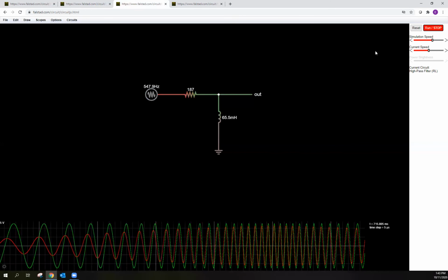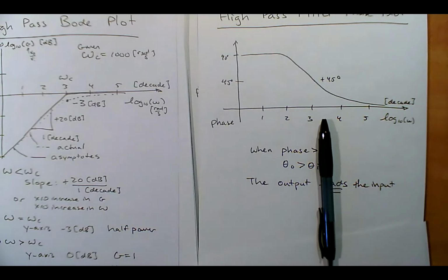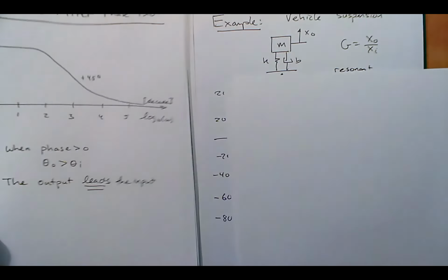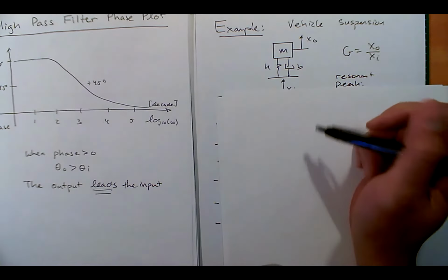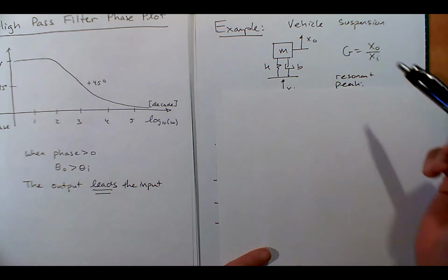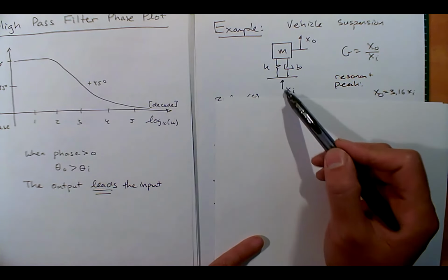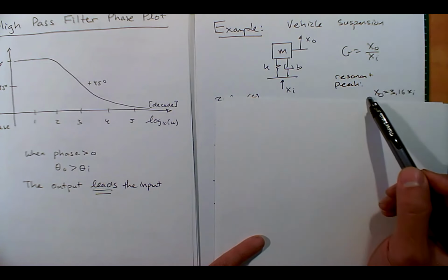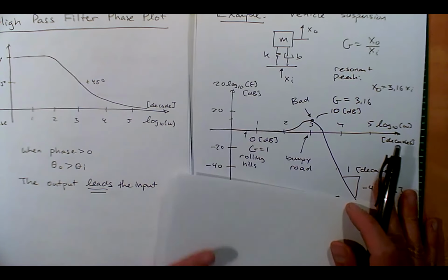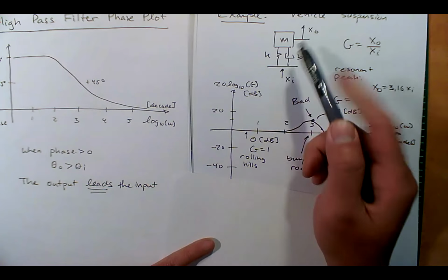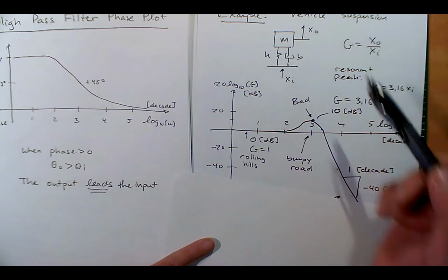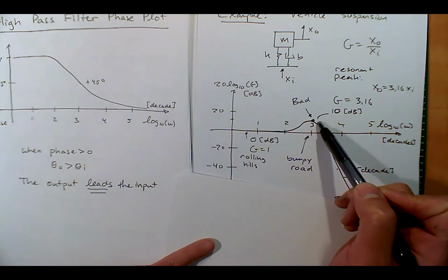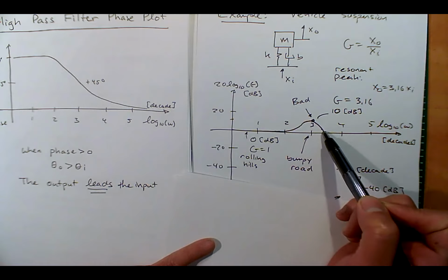Okay, let's go back to the doc cam and look at our last example. This is for fun, but I don't know if any of you are car guys, but a vehicle suspension can be thought of as a mass, a spring, and a damper, right? And what you could do is think of the road as the input, bumpy, bumpy, bumpy, and the output is something you want smooth, right? And what you might have is another Bode plot. If you don't tune your damper and springs correctly, at the wrong road interval speed, you might feel this resonance. And all of a sudden it's really bumpy, right?